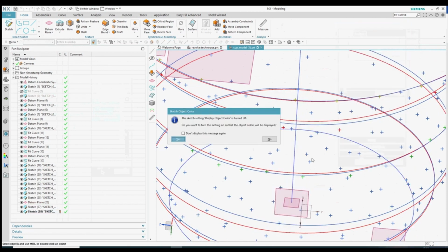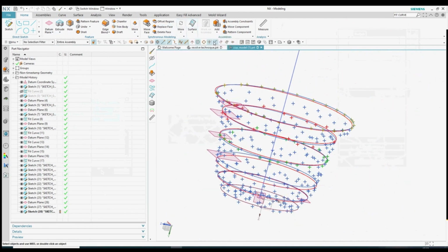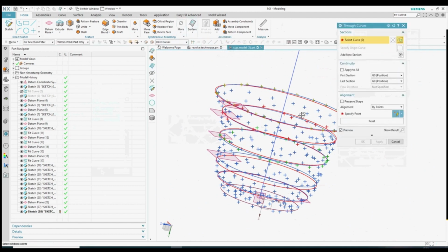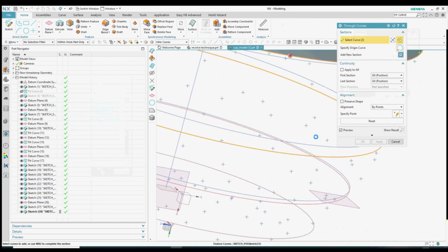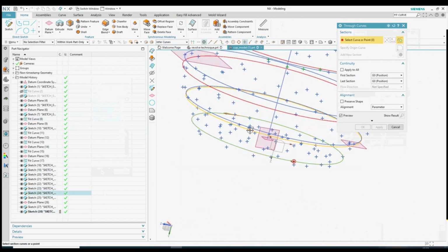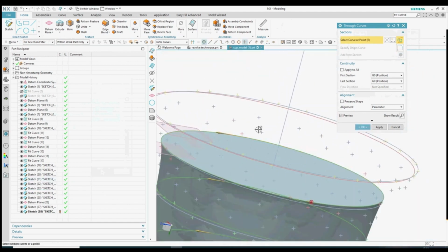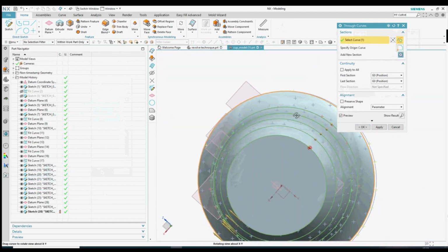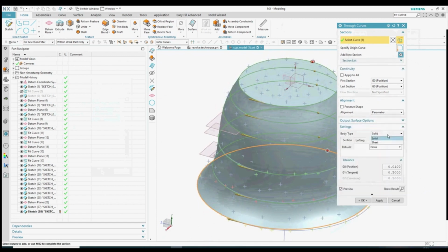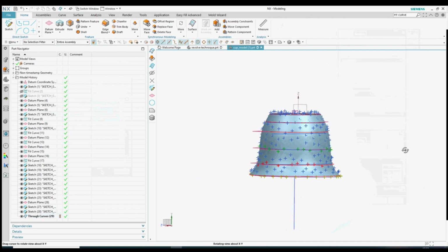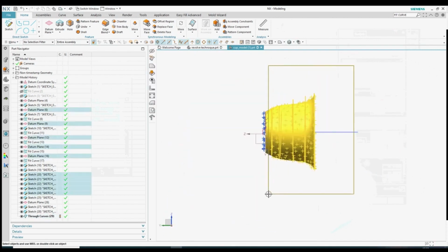You can use the through curves option to join curves to curves and also curves to points. In this model, you can use the through curves option and guide all the 6 curves and end the model by selecting the last point. However, I want to show you some other techniques which will be beneficial. Therefore, I'm going to leave my model unfinished and not select the point. So it will be a hollow object like so.